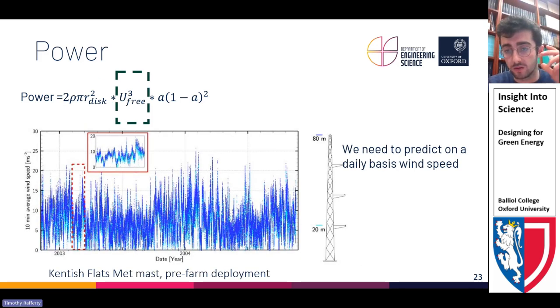Someone said velocity. Yeah, so this is actually where there is now a big wind farm. This is the data taken from it. And you can see over the year, you get this high variation in velocity. And because it's cubed, the impact of it is massive. So if you get 2 meters per second, well, it's going to be 8, that will come into that equation. So you can see how that gets cubed up. The differences get cubed. So knowing there's good wind speed is really useful.